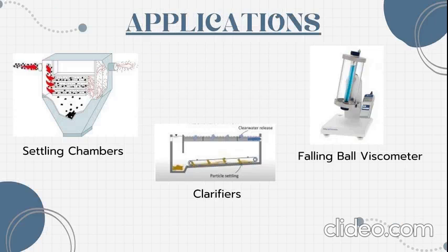Now let's discuss engineering applications. One application is settling chambers. It is used to remove dust from gas streams. When gas enters the large chamber, the velocity decreases and the particles settle due to gravity. So we can calculate the minimum particle size that can settle.